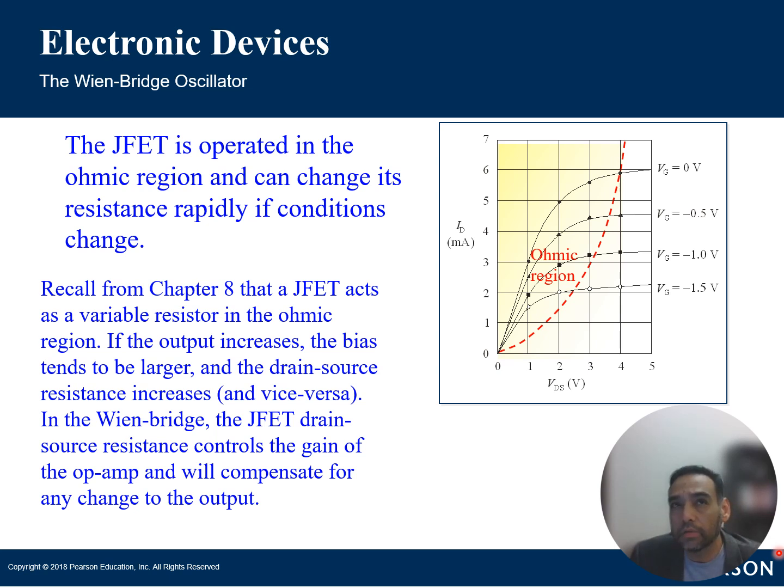The automatic gain function on your TV or your car stereo that maintains that smart sound system, right? So it doesn't get too loud or too soft. It might be something like this. If it's not, you could probably design something like this to work. It may not be the best, or maybe exactly what you need. So again, operating the JFET in that ohmic region allows for that precise control of conductance, and it makes it very useful where linear amplification signal processing is required.